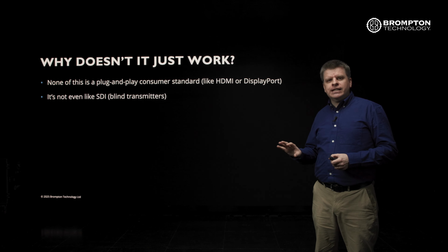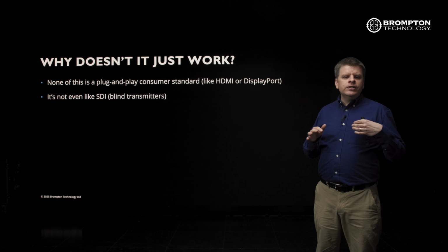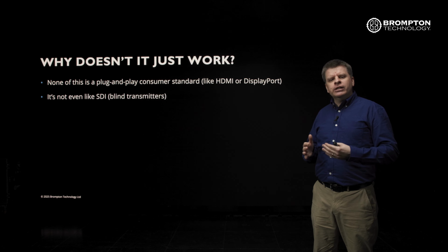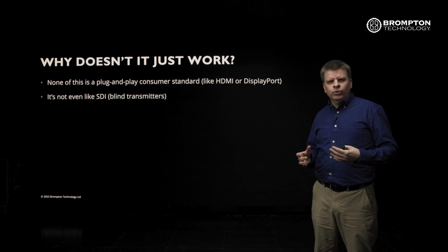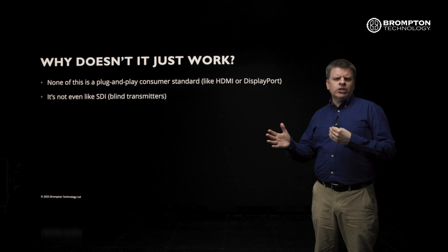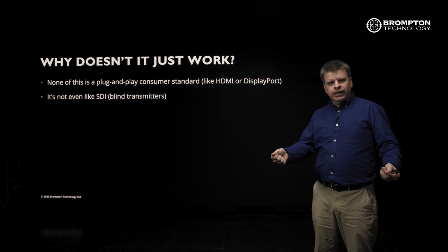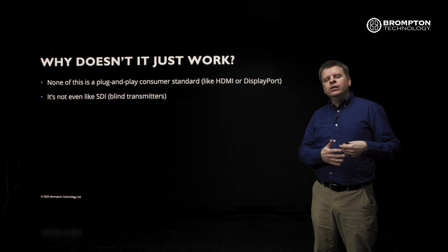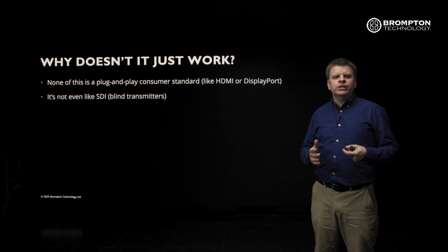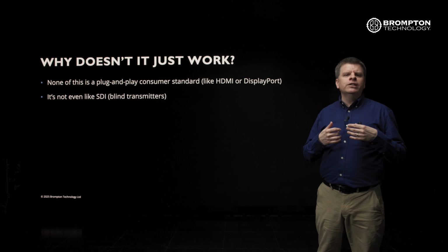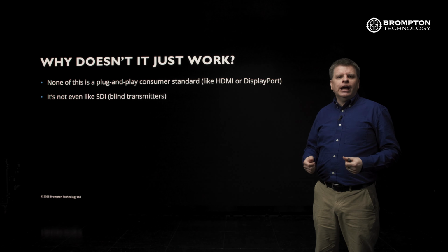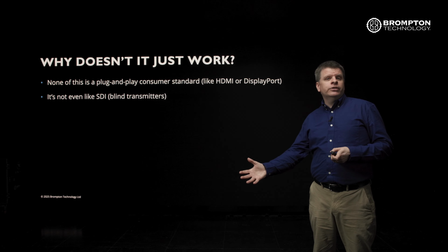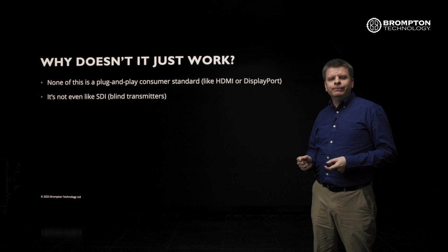And it's not even like SDI, which is a little bit different to HDMI and DisplayPort. So HDMI and DisplayPort, there is essentially a conversation that goes on when you connect up a cable, and the source and the receiver essentially agree what video standard they should be using, what resolutions are supported, what frame rates are supported, and the end result of that should be that the receiver is able to show you a picture.